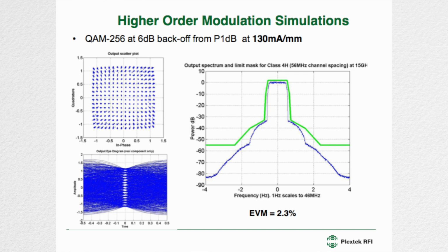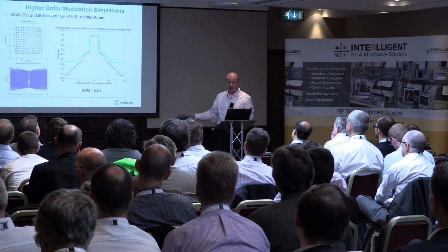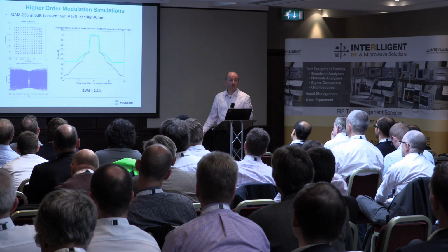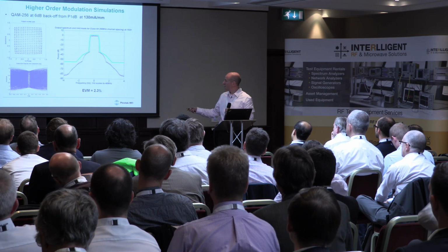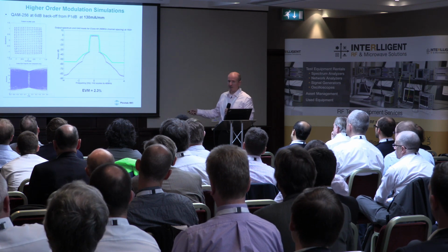You can see the eye diagram here. The key is that we're looking for spaces. These are the eye openings, and this is the sampling instance, and it's only going to work at the sampling instance. This ISI here and here is caused by the root raised cosine filtering, which you had to put in to get the modulation sidebands down. It's all quite involved to go into in detail. There is more information on our website for those who are interested.